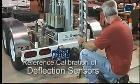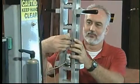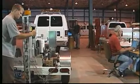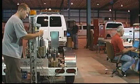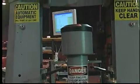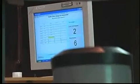Calibration of the deflection sensors starts with reference calibration versus the accelerometer. The goal here is to calibrate the sensors versus a reference device to ensure accuracy. This is done by placing the deflection sensors from the falling weight deflectometer along with the reference accelerometer in a large stand. A series of drops are performed where the reference accelerometer and the sensors from the FWD see the same deflections. After one trial is done, the sensors are rotated relative to the accelerometer and a second trial is completed. A third and fourth trial may be needed in some cases. The results from this reference calibration are used to create a series of interim gain factors for the deflection sensors.